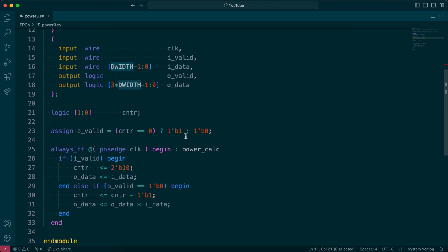Basically, all we need to do here is to pipeline our design. This is the best known technique to improve the throughput of a design. And pipelining means that we want to be able to store the value, because data comes in, right? But the reason that I cannot do anything until this calculation is done is that as soon as I change data, everything is going to be messed up. I lose the old values and I cannot do anything with that, right?